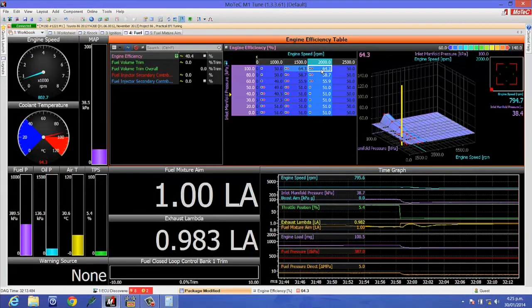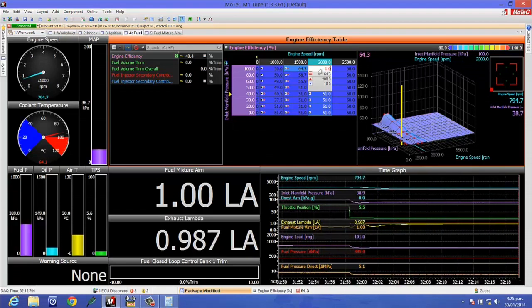This means the numbers are going to be close at this RPM range when we start tuning. Since we can expect the engine's VE to increase as we move from 1500 to 2000 RPM, the numbers are likely to be higher than what we had in the 1500 RPM column, and there are a couple of time-saving tricks here to help you. First of all, before tuning the 2000 RPM column, I'll usually add 5% to the entire column. This is a guess at how much I expect the airflow to increase at this RPM range.